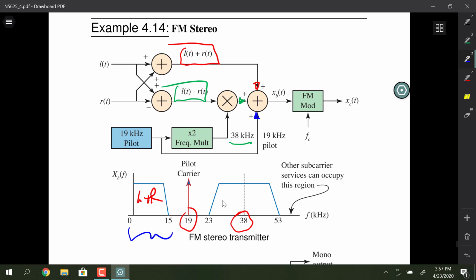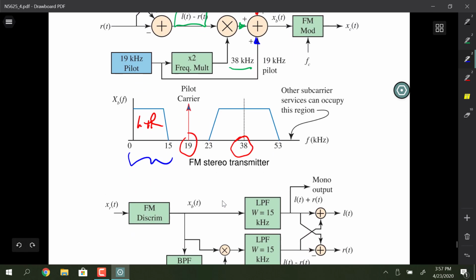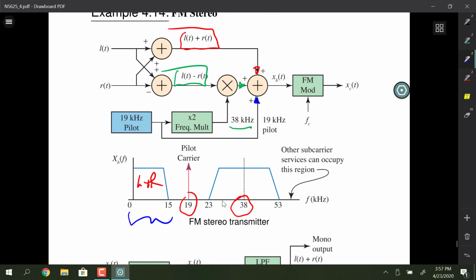Well, yeah. No, we 2 times frequency multiply the right carrier with the pilot signal. Okay. So that it's at a different frequency spectrum than the left. That's why there's 2 different humps. Right? You're talking about in the picture down here in the middle, the spectrum. Yeah. There's 2 different subcarriers. There's 3 subcarriers. One that's unmodulated. That's the pilot, and then there's the left plus right at baseband. Starts at 0, and then there's the double sideband up at 38, centered on 38.